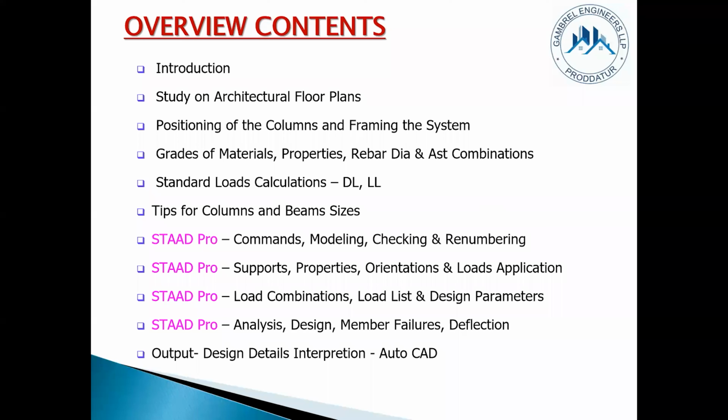Such is the key information which is supposed to be calculated by us. We are supposed to finalize the column positions, finalize the member sizes, and take the grades of materials. Then model it, calculate the loads, apply them, make load combinations, and run the analysis to analyze the structure. If a member fails, redesign it. And when you are finalizing the member cross section, focus on the practical requirements.